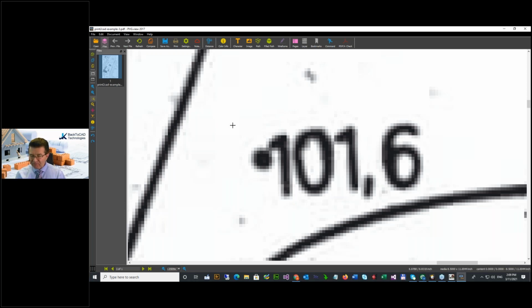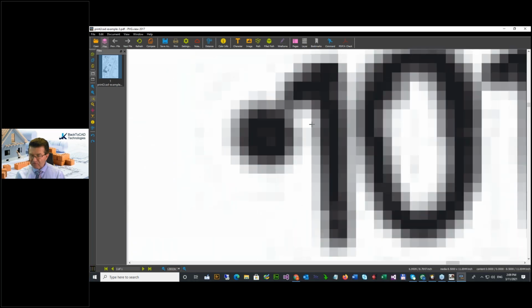So now the most important parameter, if you want to vectorize this picture, is the threshold for the color black and white. Because vectorization or optical character recognition is every time made only on a black and white drawing. And this is a grayscale drawing. The correct threshold will be this kind of gray, which separates this black from this black.